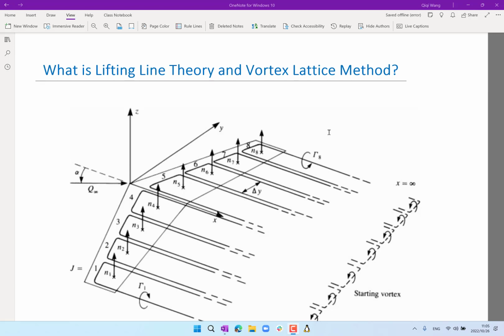Okay, good morning. So last time we derived the induced flow using this kind of method for a rectangular wing. What we have done is we have taken the rectangular wing and, using the lift per span, figured out how much circulation there is on this wing, right?